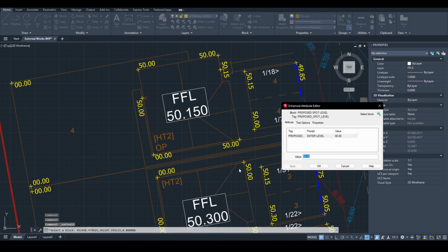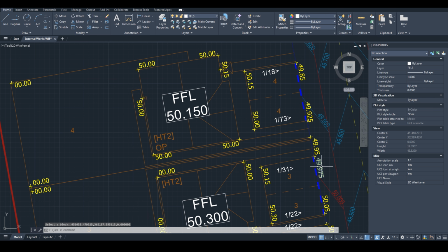This is because I will set the corners to 150 mm below floor level on the lower plot, and that will dictate the levels on the corners of the adjacent plot, and we can then show the required exposed brickwork. If we did this the other way around, we could end up tanking the lower plot, or requiring double damp proof course. I will explain this in more detail shortly, or you can refer to the cheat sheet.